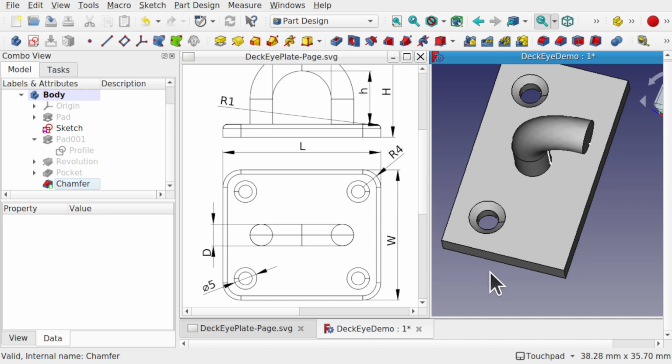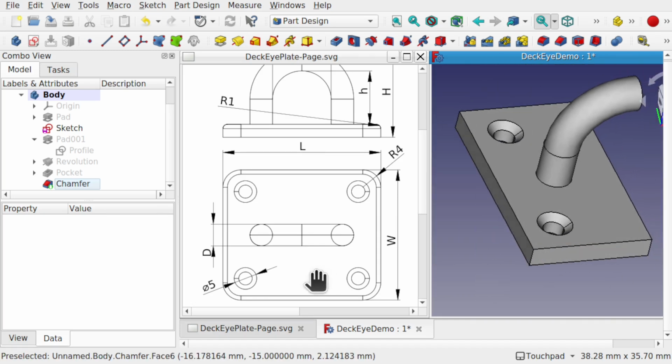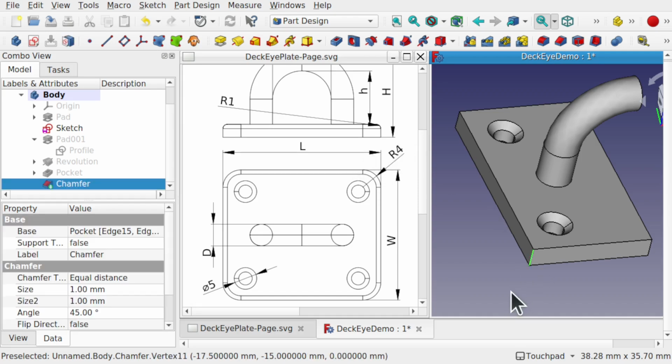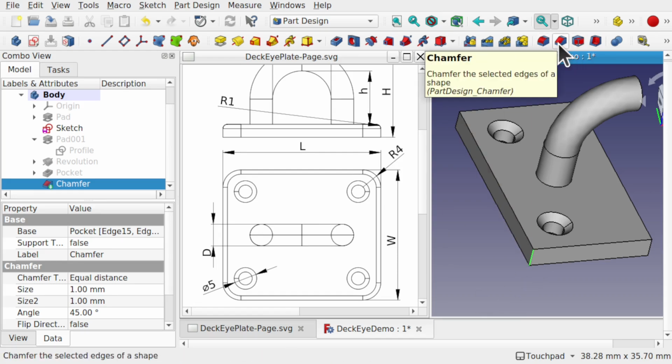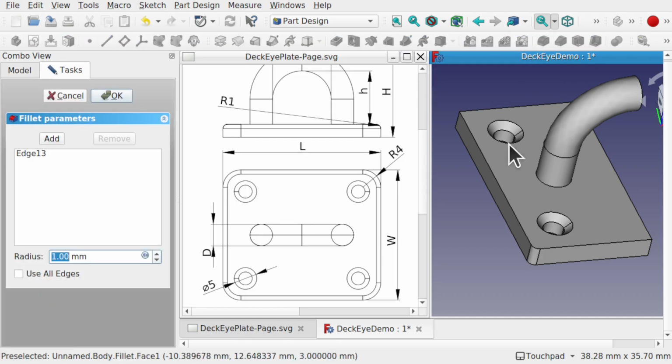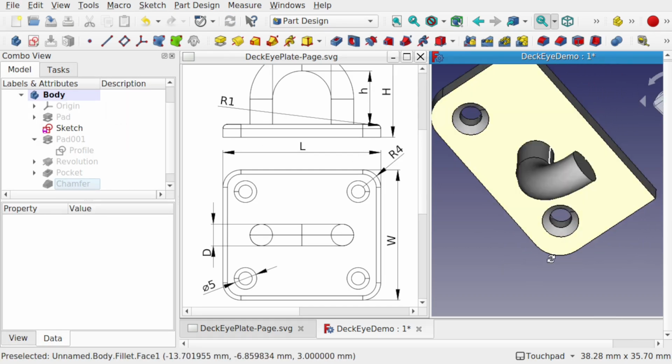We now need to add the fillet. So we look here, we can see we've got this radius here of 4mm. Let's click on this line, and this time we can add it from the toolbar. This will be in the apply dress up again, but we're just going to use the fillet. You can see that's filleting off that edge, and we want a radius of 4mm. Let's add another edge and take this edge over here as well, and hit OK. So we've just cleaned this up.